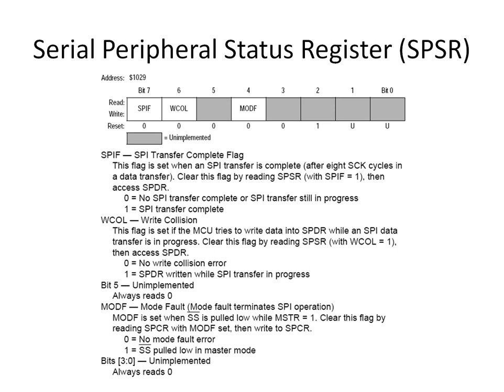So if we send out over the SPI port, we need to be attentive that we don't try to transmit immediately thereafter. Why? Because it hasn't finished transmitting what you told it to begin with. So we need to wait or pause to ensure that whatever we told it to send out has actually finished transmitting before we send it another byte. Therefore, we need to check this SPI transfer complete flag to see when it's gone high, because once it's gone high, it means that the transfer is complete.